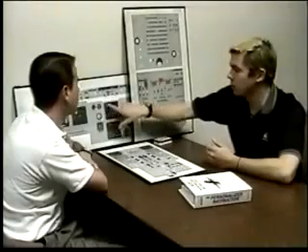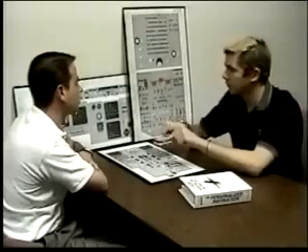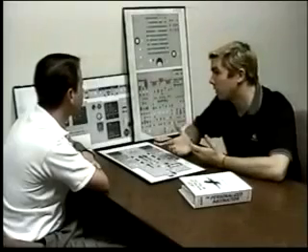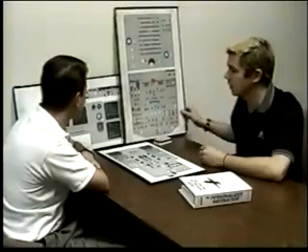So when I select the good one into N1 mode, if I have an unrated situation on the bad engine, I can match the two engine indications up to protect myself on the weak engine. If both were to fall into N1 unrated mode, I'd have to use flight manual computations to determine what my thrust settings would have to be.